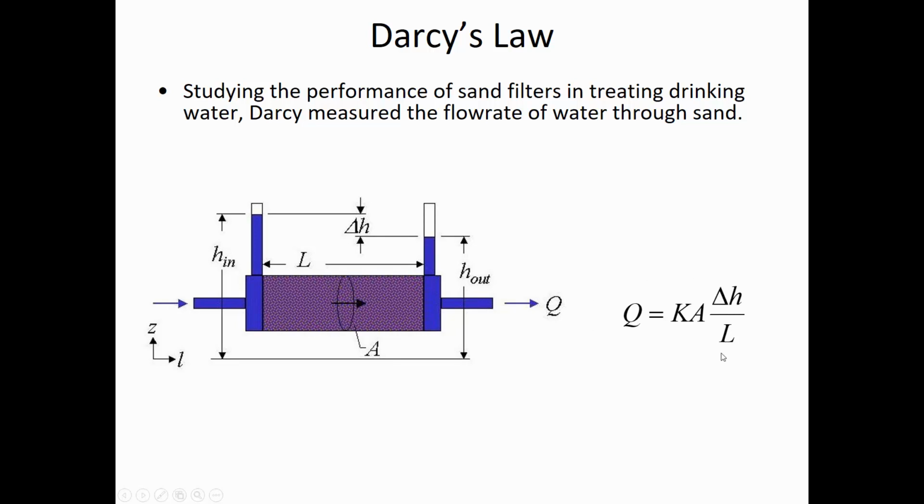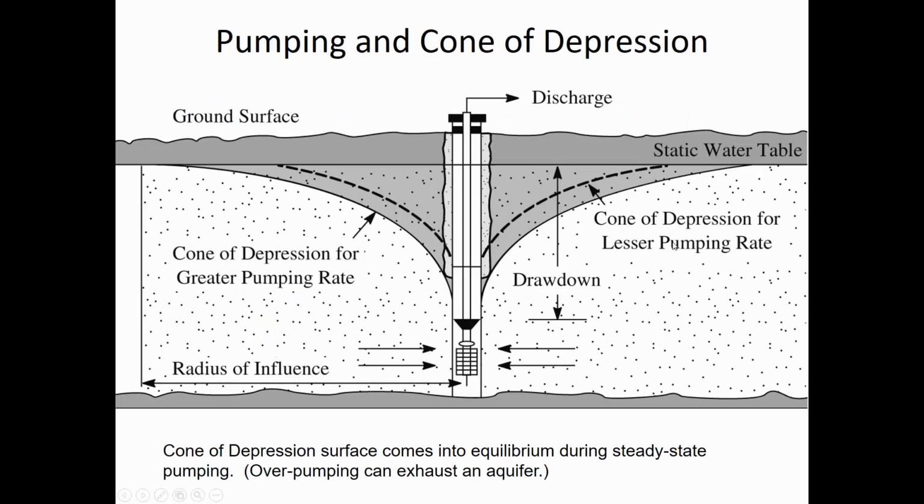This also influences how productive a well will be when you drill down into an aquifer and you're trying to find out a certain flow rate out of that aquifer. We use some of the same ideas that are found in Darcy's Law. Hydraulic conductivity is a key factor there. Some other terminology, what we're seeing here is an unconfined aquifer.